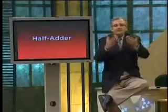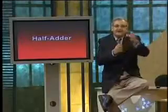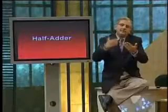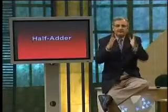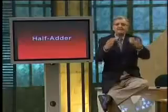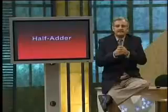Now, when you connect different adders together, of course they add the two numbers as well as the carry borrowed from the previous two numbers. So your adder circuit should have a third input. It should have 2 bits to represent the 2 numbers as well as the carry in. It should have 2 outputs, the carry out and the sum out.